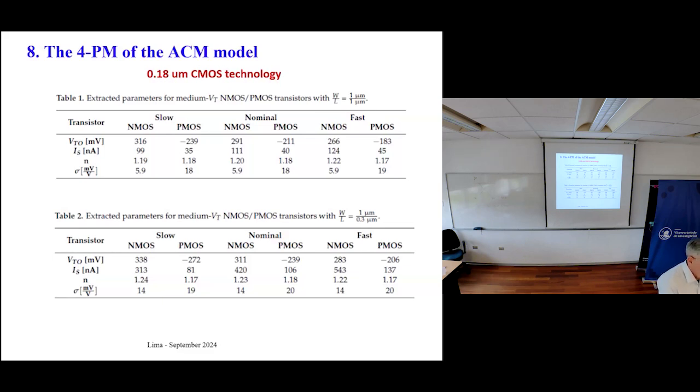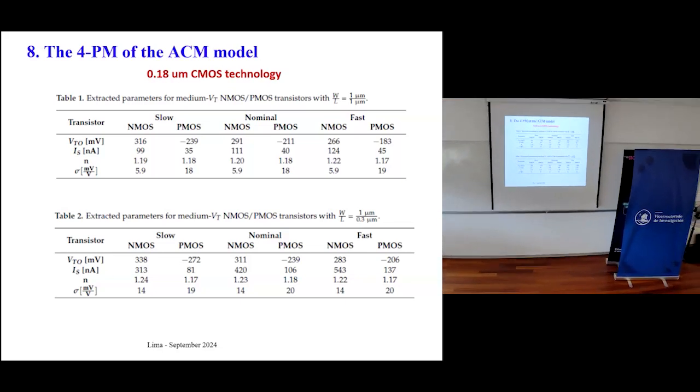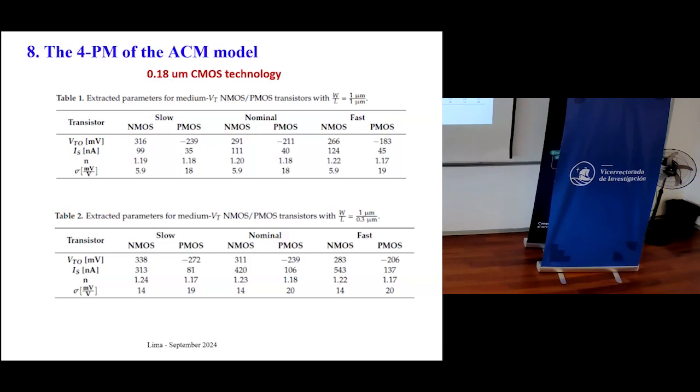And the lines cannot be very thin because they can open. So you have lots of rules, more than 200. But you don't check this personally because if you have a circuit with 1 million transistors, you cannot do this. You have EDA tools, electronic design automation tools, who do this for you. If you violate some rule, they tell, oh, you have a problem here.